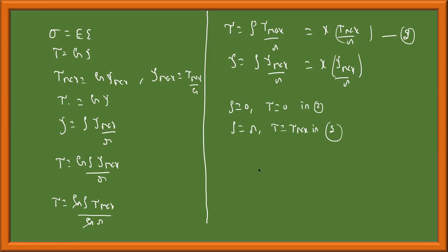So the shear stress distribution, if you remember, is like this. If I take a shaft, the shear stress distribution on the element will be like this. If you plot this, this is how the shear stress distribution will be. I will take the surface as circular. It is uniform throughout along the length also. Due to the complementary shear stress theorem, if this is like this and the opposite face like this, if you take a section also, the same shear stress will be there.